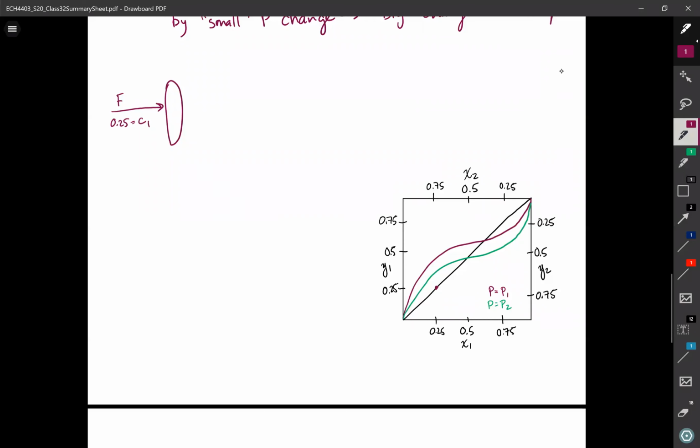So if my composition is 25% pure component 1, what are the compositions that I'll be able to get out of the first distillation column? Assuming everything goes perfect, and say we have a ton of stages and we reflux a lot, my limit to what I'm going to be able to get out of this distillation column is going to be nearly pure component 2. So this is why I've written this second axis up here, because I think it's helpful to realize that by specifying what component 1 is, you can also look at what component 2 is. This will be helpful in a second.